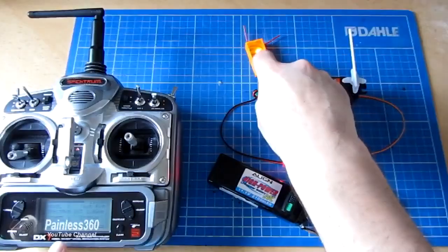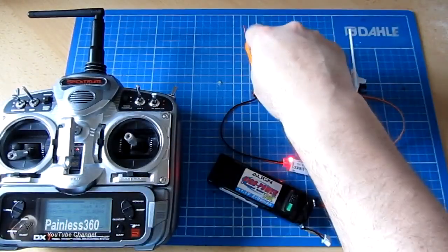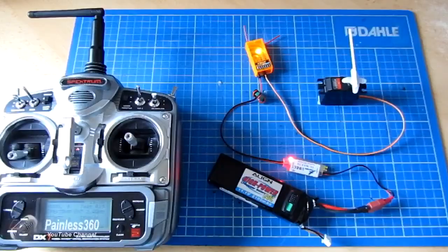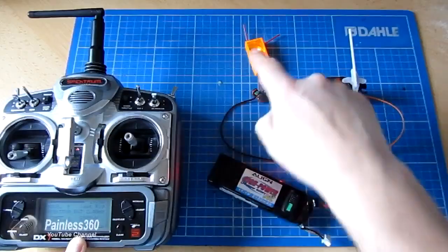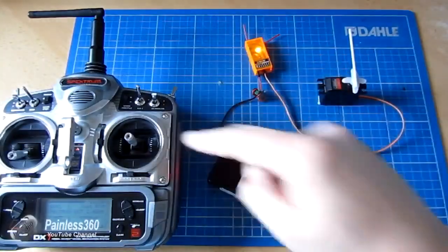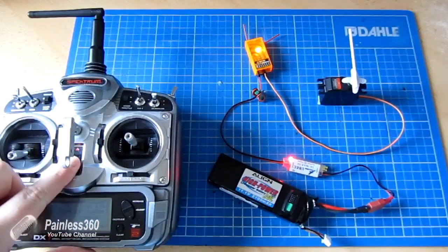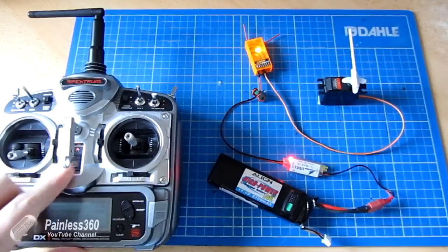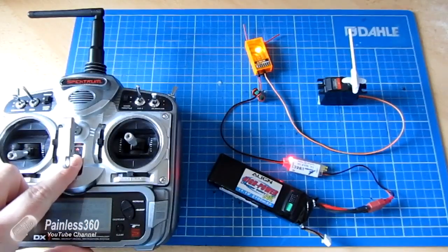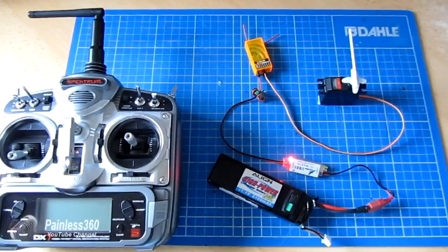The process of making that connection between your radio and your receiver is called binding. You only have to do it once, and once it's done, these two are a pair and they will only talk to each other, and this will only activate when the radio turns on. So to illustrate the point, if I turn this radio off, you'll see that the receiver will realise the radio is no longer there and take the connection light off. If I turn the radio back on, it'll take a second to connect, and there we are, we've got our connection back again.